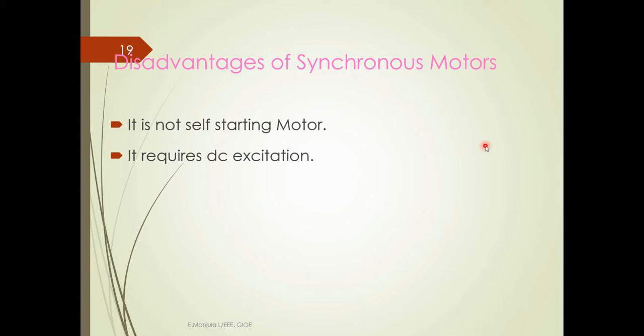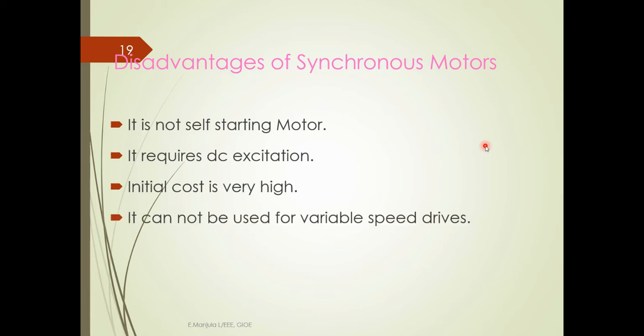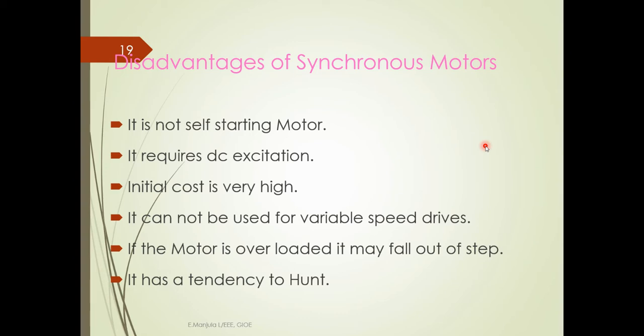So it requires a DC excitation. Initial cost is very high, and it cannot be used for variable speed drives as it is a constant speed motor. And if the motor is overloaded, it may fall out of step. It has a tendency to hunt.